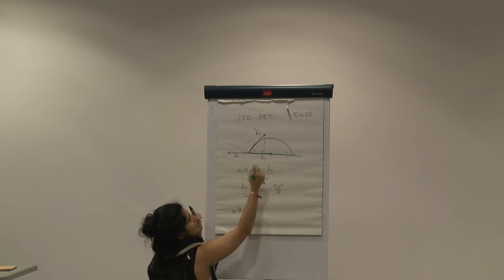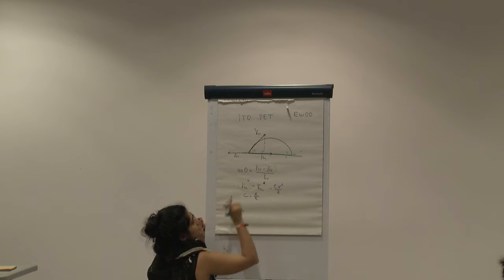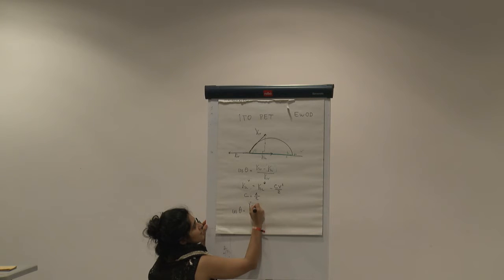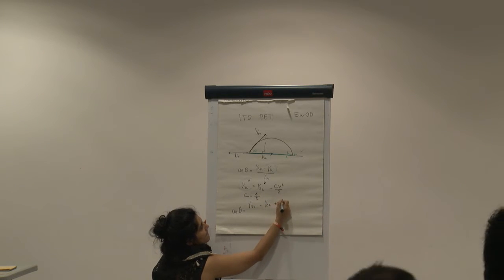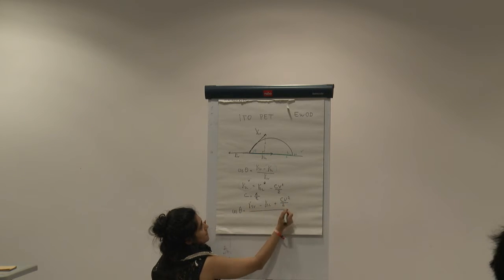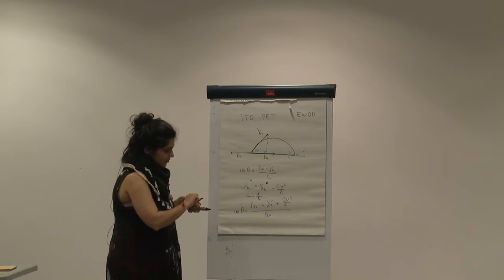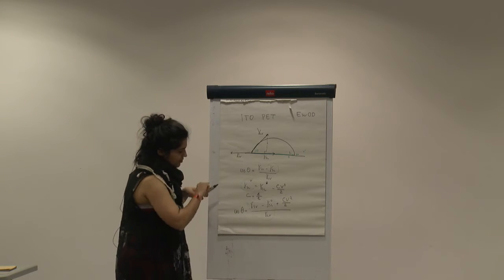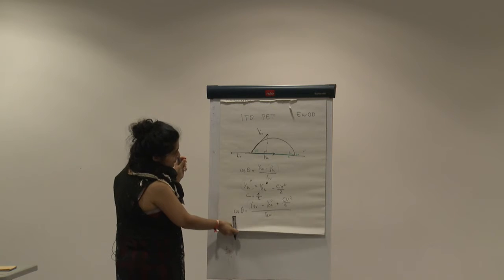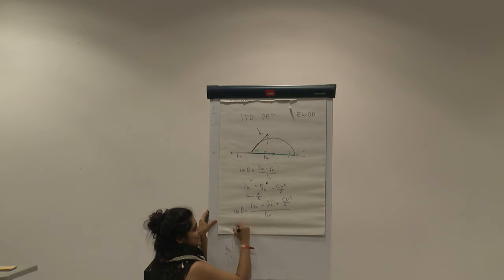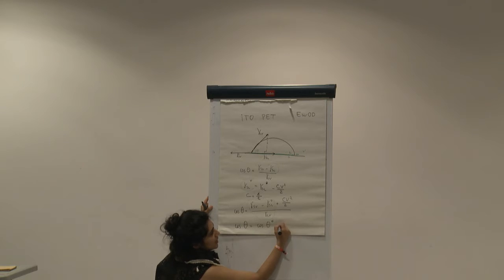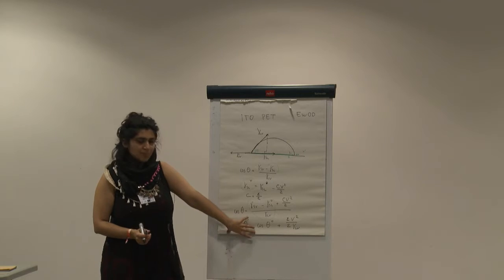The surface tensions become the solid-vapor minus solid-liquid over liquid-vapor, and this is cosine theta 0, plus I'm replacing the capacitance with this value, so we have epsilon V squared over 2 T gamma. Now, this is called the Lippmann-Young equation.